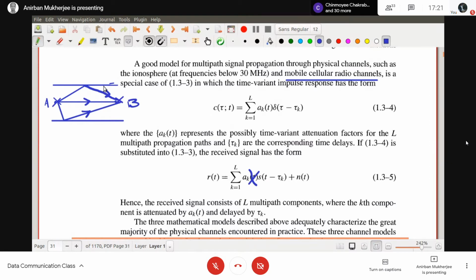On some path, after some time, the signal faces a problem. Rain absorbs the energy, so raindrops cause a kind of amplitude dip and the attenuation is more. That is why it is prudent to use a time variant path.